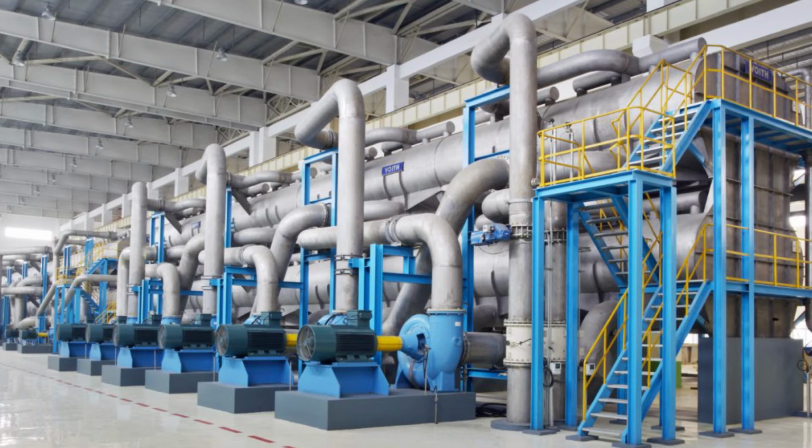Also, the size distribution and shape of ink is controlled using the enzymatic process to increase the efficiency of the size-based flotation process. This is done by selectively varying enzyme composition, charge, and residence time, as well as varying other additives and pH in the system to effectively dislodge the normally large, flat, and rigid ink particles into much fewer and non-platelet forms. The enzymatic deinking process also improves freeness compared to chemically deinked pulps.